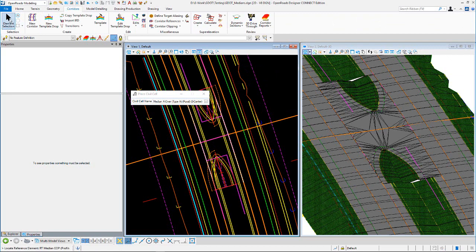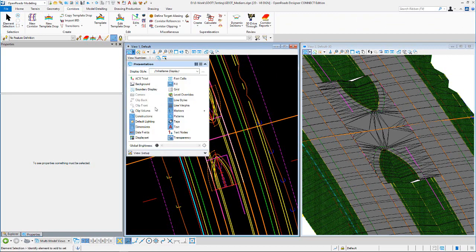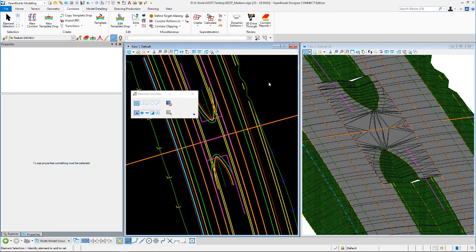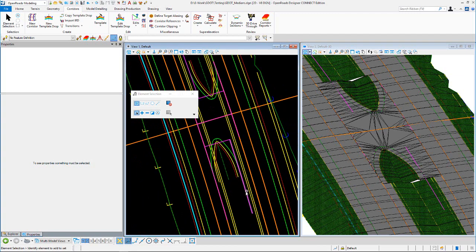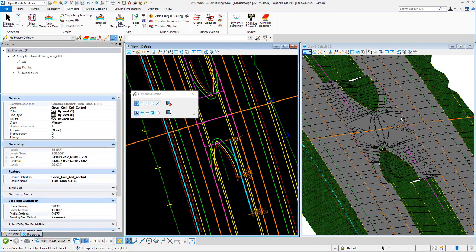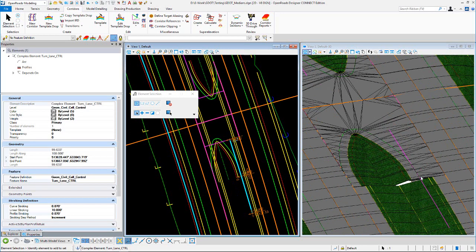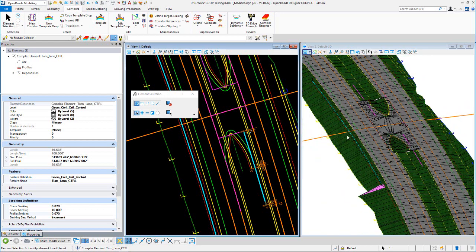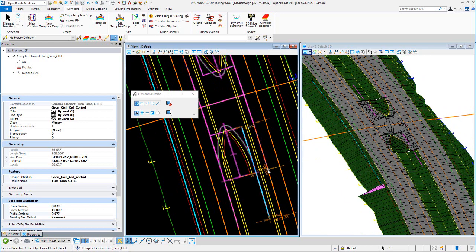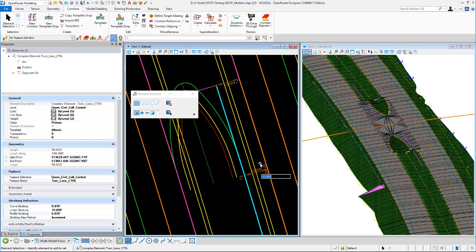Okay, so I'm going to turn construction class elements off. And then just looking at a few of these edits, the first I want to mention: initially, the crossovers are placed where you do have room to add a turn lane, but if you didn't have a left turn here and you wanted to take that out, you could just set that to 0.